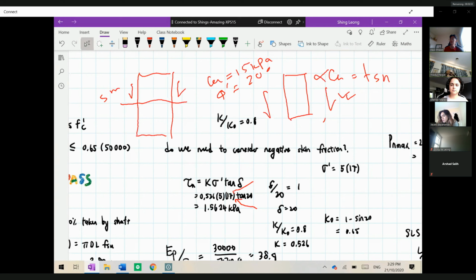reverses the resistance downward, what is the phenomenon that is happening at that time? That means the soil is moving downward at that moment. Yeah, the soil is moving downward, and then it's pulling the whole pile around the skin downward. And that happens basically through a process known as consolidation. And if consolidation is happening, that time we call that drained. Consolidation is a drained phenomenon, isn't it?